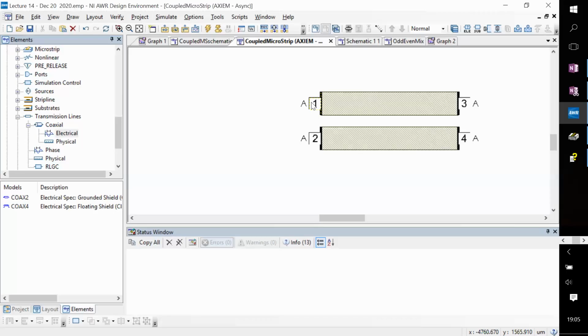This is the simplest type of directional coupler one can make, but there are many other designs where you can improve upon this, give more bandwidth. So we had discussed, in the context of the impedance transformer, that it also works only at one frequency, but then you define a range of operation. So what does it mean that it won't work? It just means that the coupling factor might not be 1% uniformly. It might vary a little bit. The isolation might not be 0. So some power will leak out of 4, but it will still be small. So those things will determine the performance of the device.